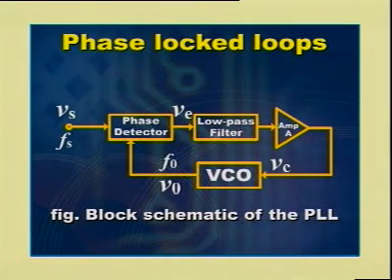So, here by phase locking phenomena, the free running frequency of the oscillator is stabilized with respect to variations in the aging, temperature, humidity or vibration, etc. So, let us consider the basic principles of the phase locked loops. The basic block diagram of the phase locked loops is as shown in figure.